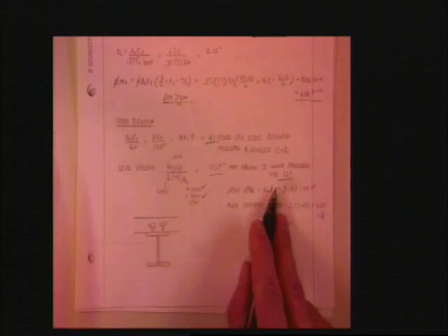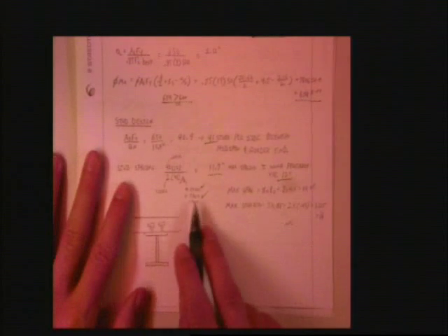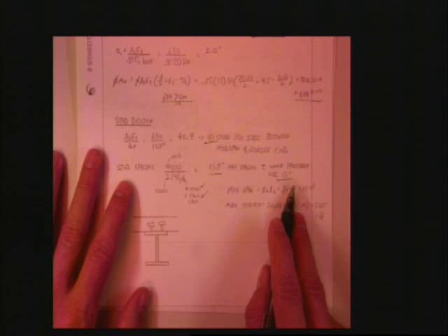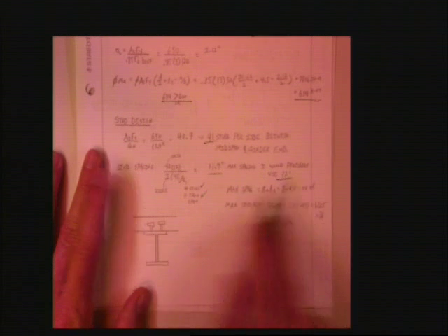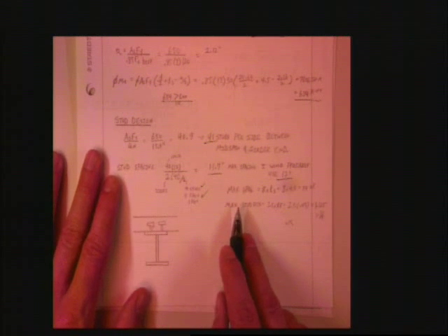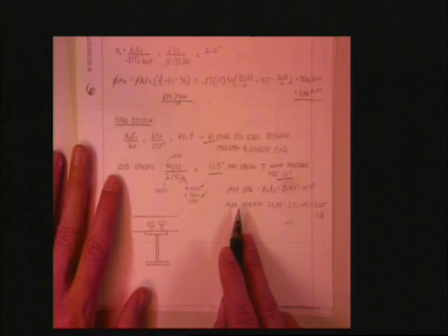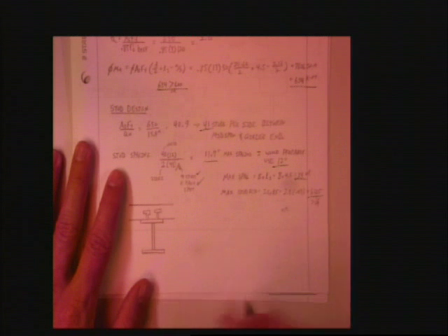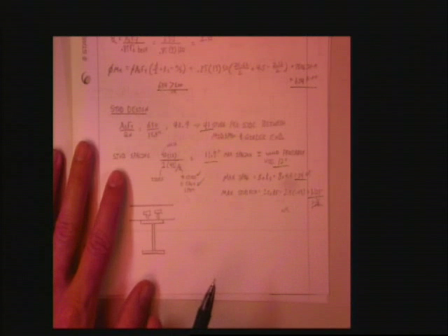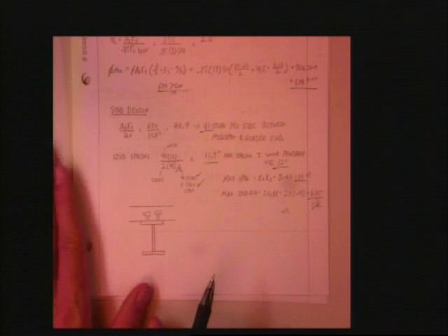And people will say, whoa, you calculated that you needed 11.7. 12 is more than 11.7. That's not conservative. Yeah, but it's like 0.3 of an inch. I'm not going to lose any sleep over 0.3 of an inch, especially when I know that this whole thing's made up anyway, and the only thing we're doing is trying to not cause slip. Does that make sense? So I'm going to use 12 inches. So we do our maximum spacing check. It's 34 inches. The maximum stud diameter is 1 1/8, and we got 3/4. Make sense?